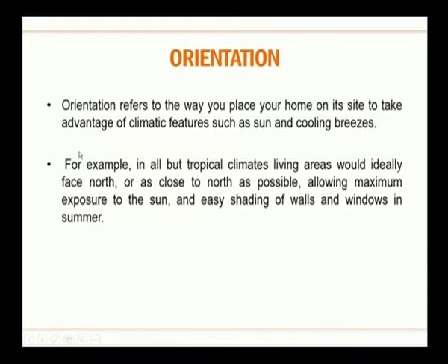So, as we said before, orientation becomes a main or basic aspect of passive design, in which you need to place your building according to your specific climatic zone to benefit from the climate. If you are in a colder region, your building's longer facade must be facing towards the west or the south, and when you are in a climate like the tropics, your longer facade must be facing towards north. So, it reduces the solar radiation which is coming inside the building, which eventually reduces the air conditioning usage.